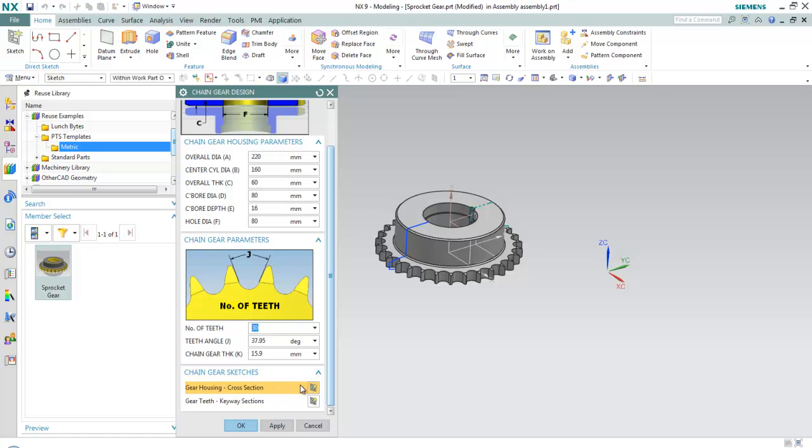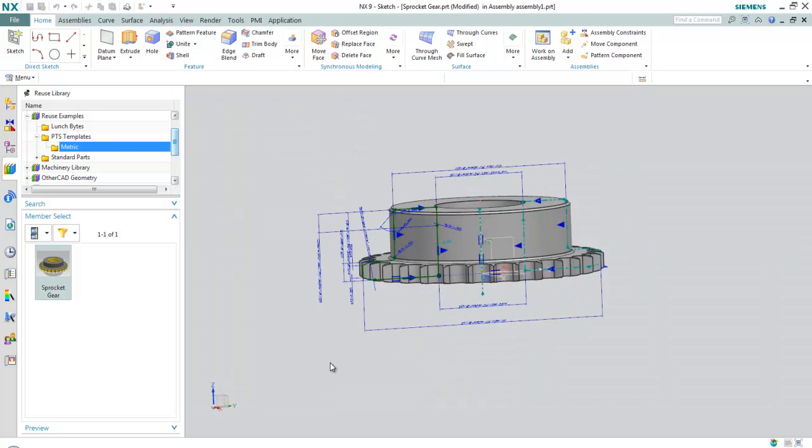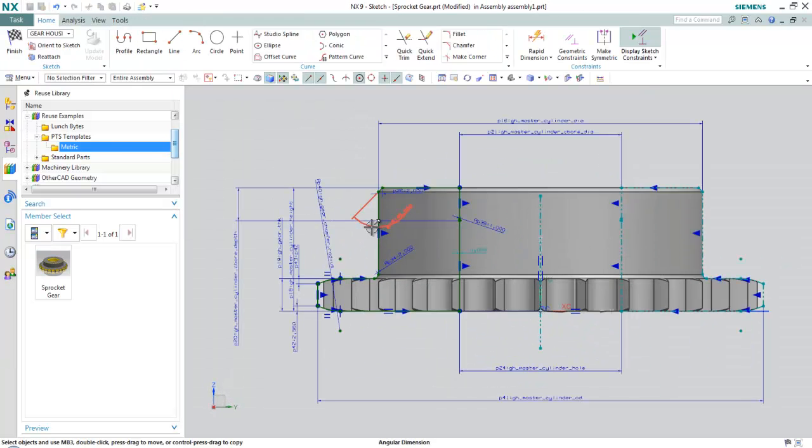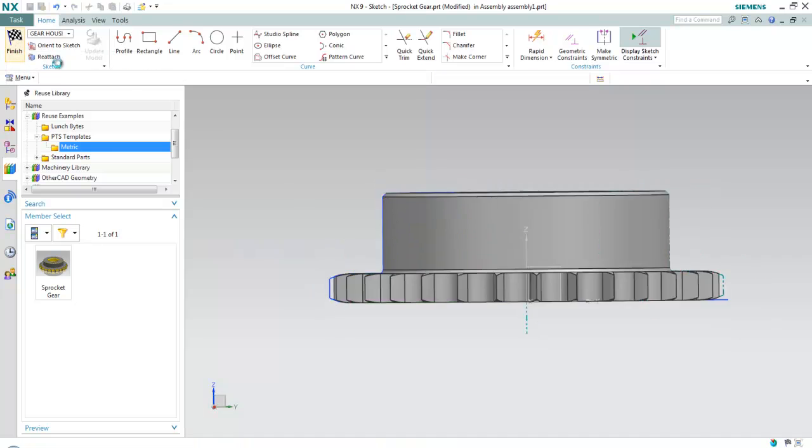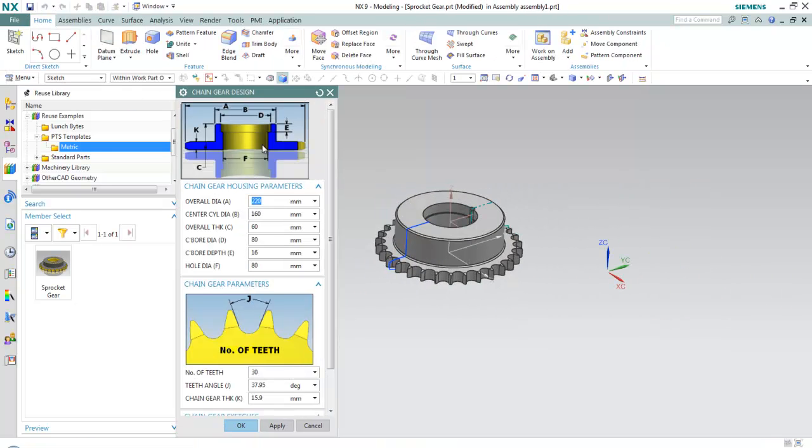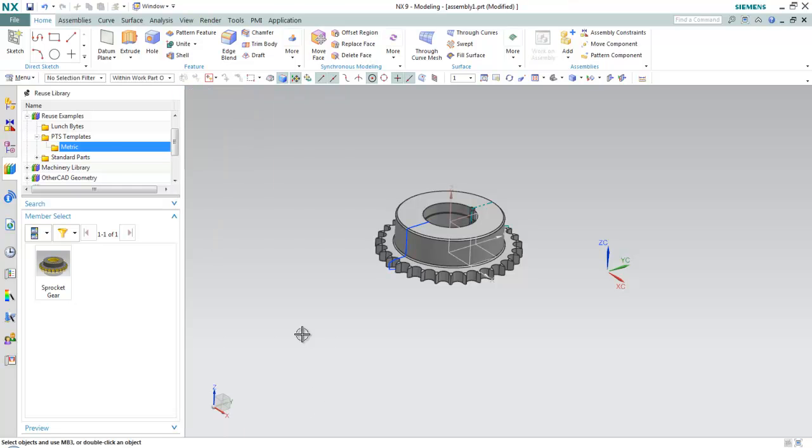You'll see that you can also access geometry, things like sketches. If I want to come in here and edit the cross section, I can get into these expressions, change the 2D geometry in the sketch, and update the revolved feature. But I'm accessing it from a nice clean user interface. So there is an example that is delivered with NX if you have a consumer license. And now let's look at how we want to create these.